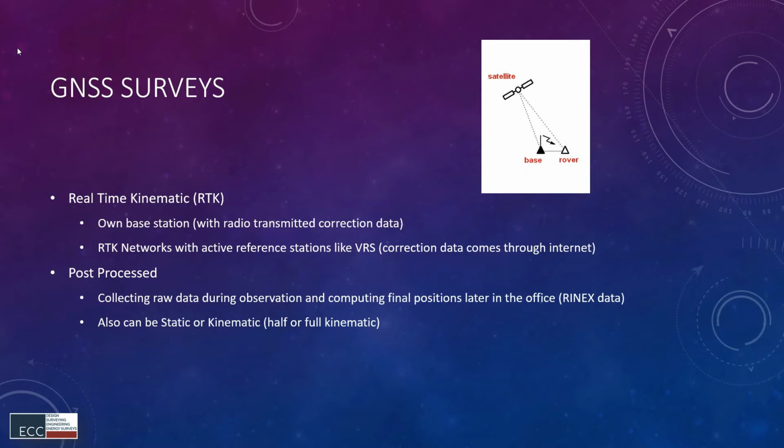I will tell you when I'm opening Trimble Business Center, there is a hierarchy system in Trimble Business Center. Basically, you can set the points' quality to unknown, survey, map, or control point, and whatever you select to be a control point is not going to move anymore.